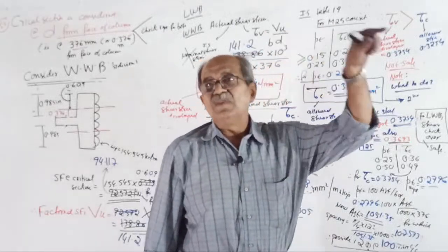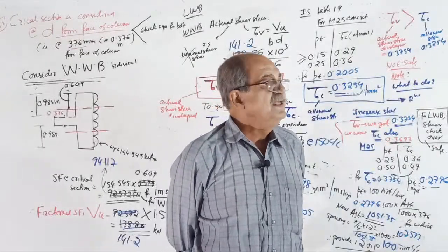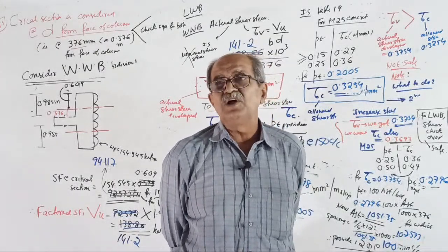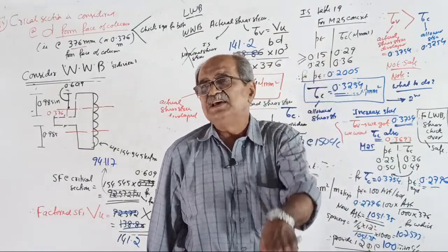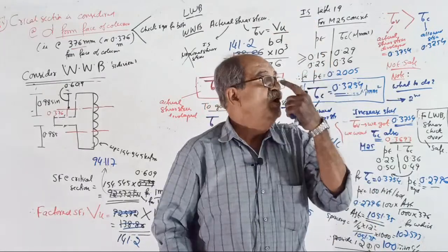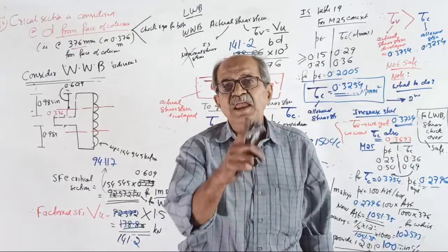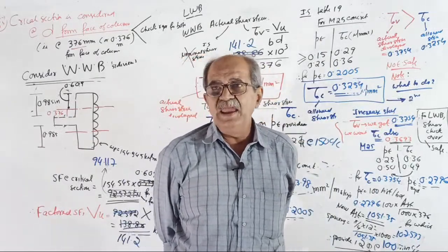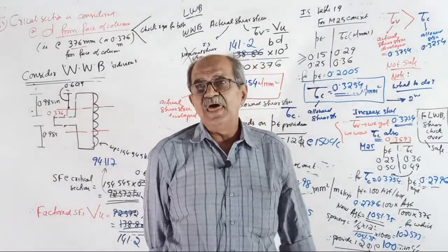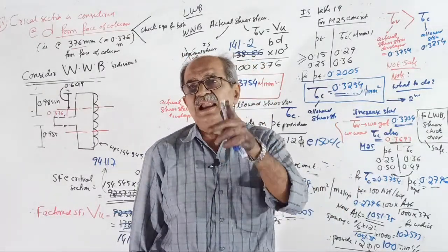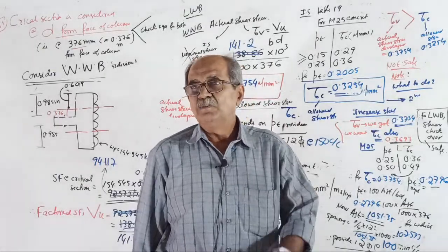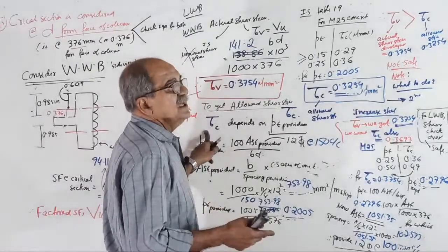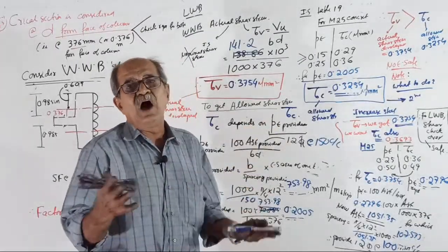So our next part is design of isolated footing. When from the column you have to consider not only axial load but M1, M2. When earthquake is there, high M1, M2 is going to come. Remember, when you consider earthquake, high values are coming. So the next question is practically important. But next time, I don't have to waste time telling lengthwise bending, that is already cleared.